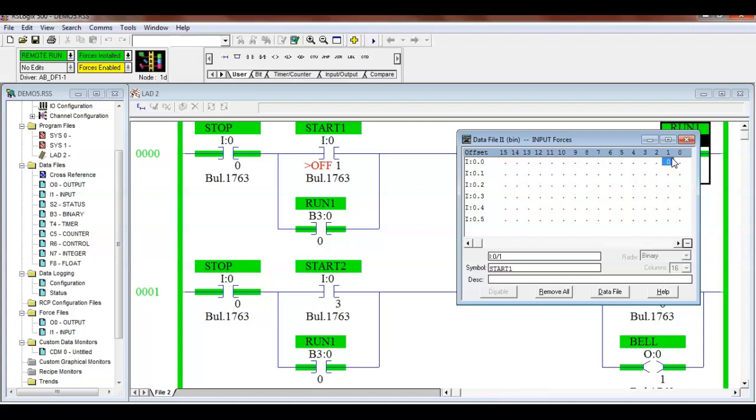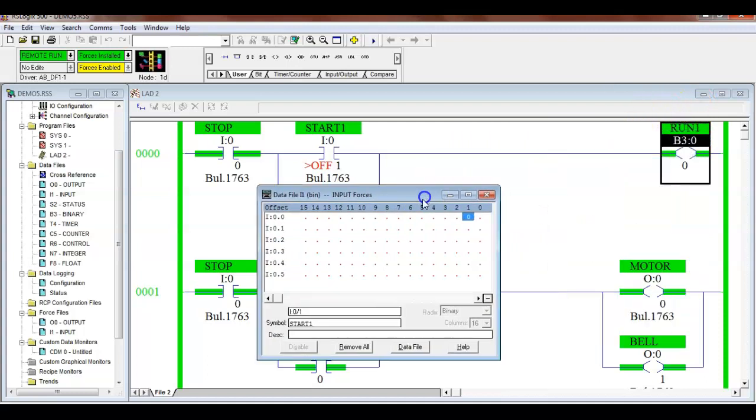And it came up and it cut him in two. From what I heard, I went over there, thank goodness. They brought him down in 2 pieces, killed him instantly. So when you force a contact, you better know for sure what's going to happen, because right now I just turned that motor on. So this motor right here just did what? The bell's ringing, I turned that motor on, and that push button wasn't pressed.